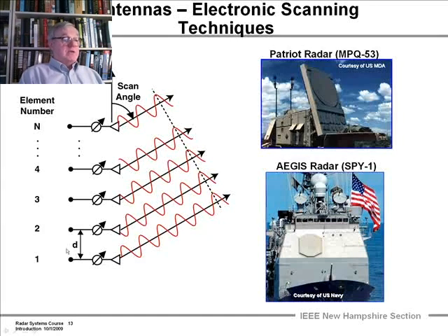But if we put in phase shifters, we can adjust the phase so that at a specific scan angle, all of the maxima of the individual waves are in coherence, and they reinforce each other constructively.